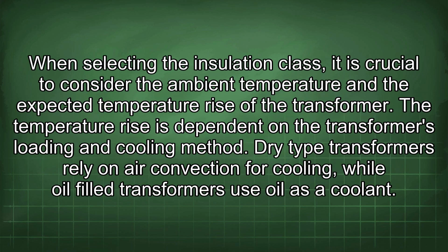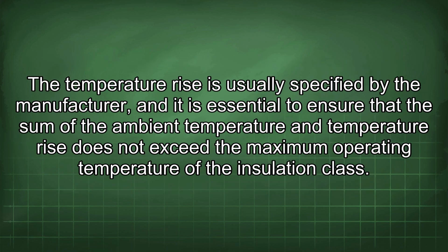When selecting the insulation class, it is crucial to consider the ambient temperature and the expected temperature rise of the transformer. The temperature rise is dependent on the transformer's loading and cooling method. Dry-type transformers rely on air convection for cooling, while oil-filled transformers use oil as a coolant. The temperature rise is usually specified by the manufacturer, and it is essential to ensure that the sum of the ambient temperature and temperature rise does not exceed the maximum operating temperature of the insulation class.